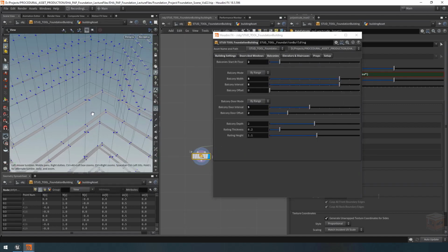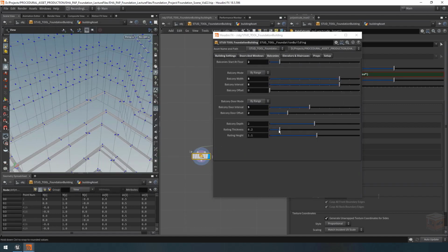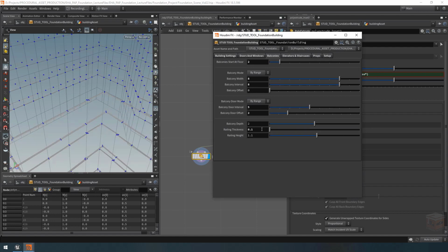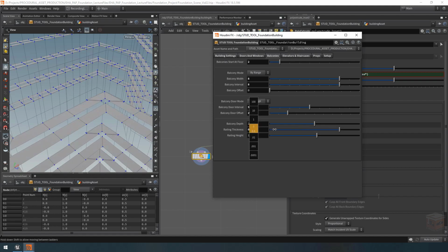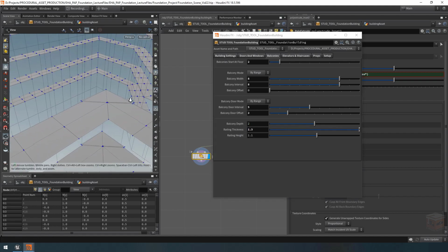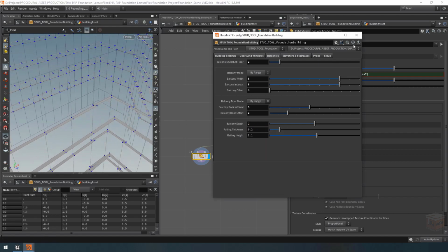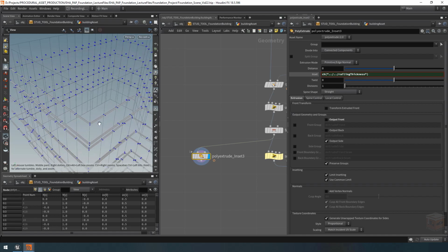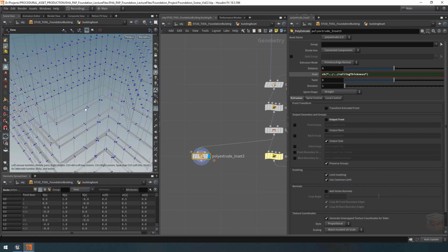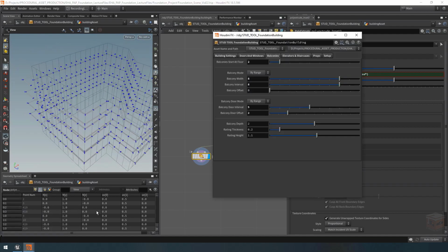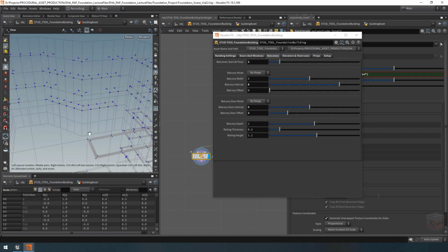Now with that, we now have a proper balcony that we can control the depth from, and it should always have at least some depth. Now it won't allow you to intersect it too far. It will eventually hit the center, but don't worry too much about that. Basically what we need to do next is clean up any of these balconies that are on the walls. And also, let me just quickly return these balconies back to how they used to be. So I'm going to change the width back to 5, so that's lower than the interval. So we have some nice shapes over here, right?